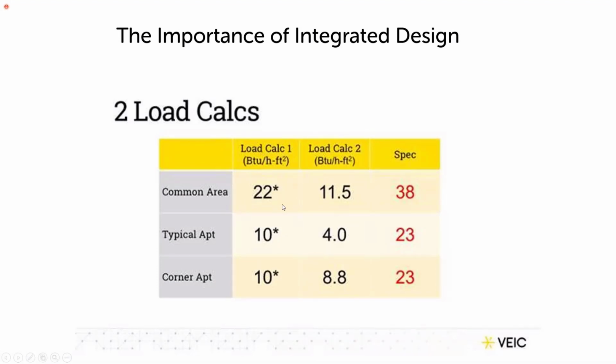And you can see these numbers were basically cut in half. But then the old methodology of padding those numbers, covering your butt on the cold days and not wanting the callback, were added to this. And this was all individual heat pump units. So each room was getting its own heat pump, which makes it an even more significant implication.